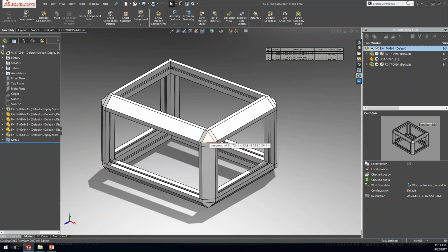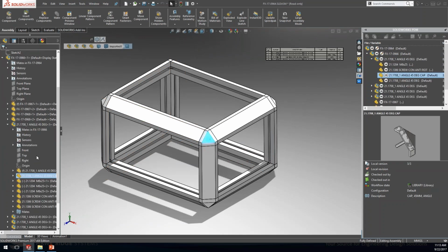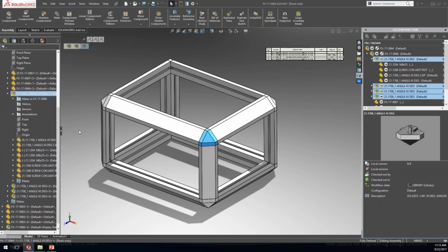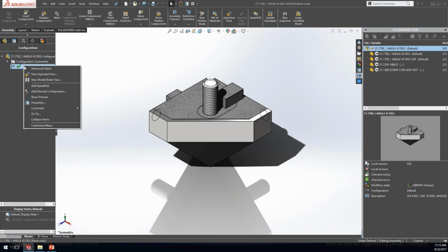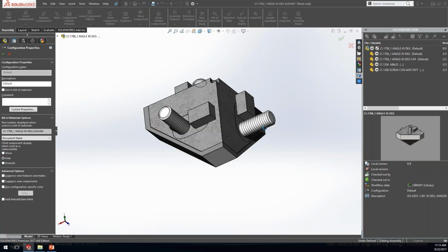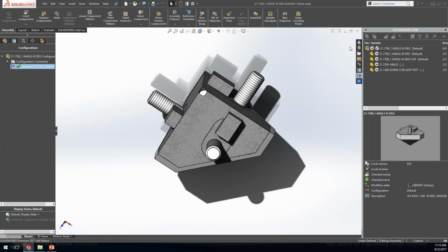So I want basically just all of these corner components, which are part of the subassembly, to show up as individual items. These, incidentally, if we look at them, have a similar option here. If we go to their configuration properties, they're set to hide. This is an off-the-shelf assembly I buy from this supplier, so I want it to show up that way in my BOMs.